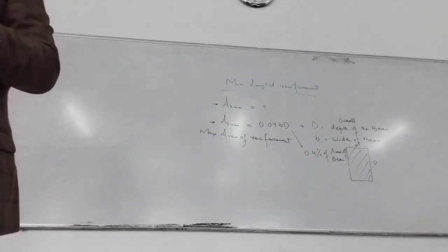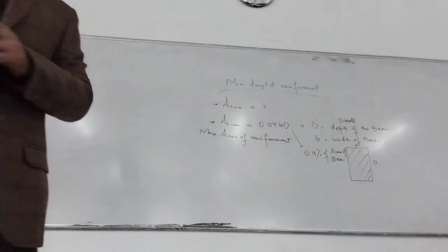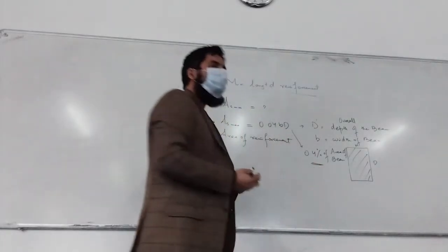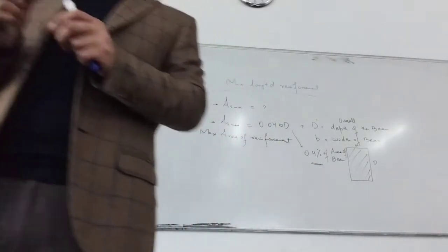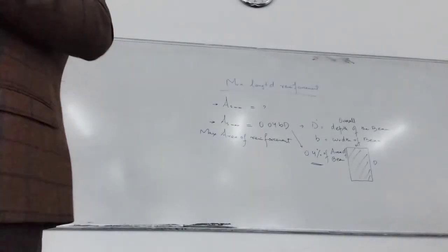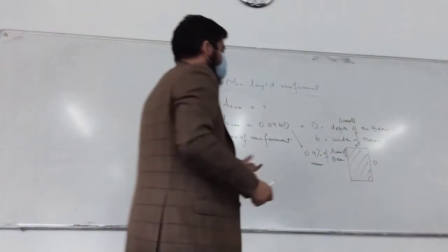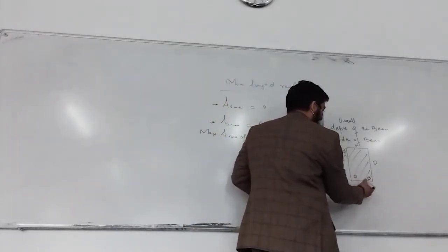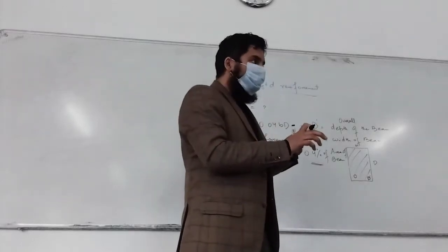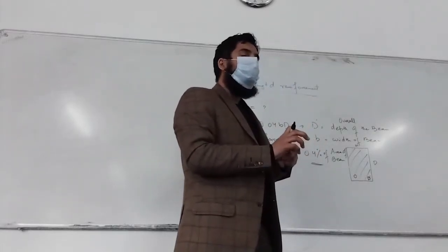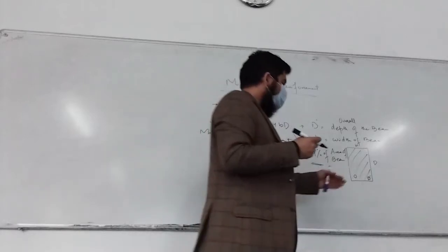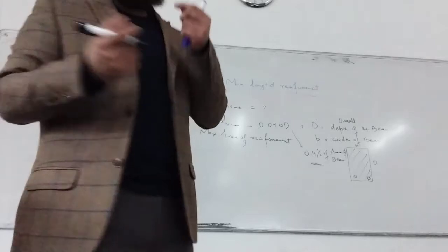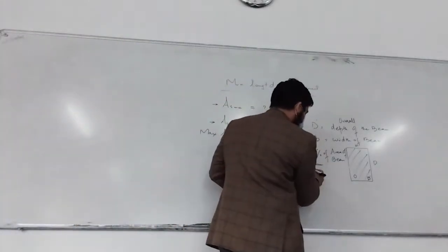Now again, why do we require maximum reinforcement? What is the purpose of this maximum area of reinforcement? Minimum I told you last time. What is the purpose of the maximum? There are two things. First of all, once we keep on increasing the area of reinforcement, it tends to become uneconomical. The section itself becomes uneconomical.